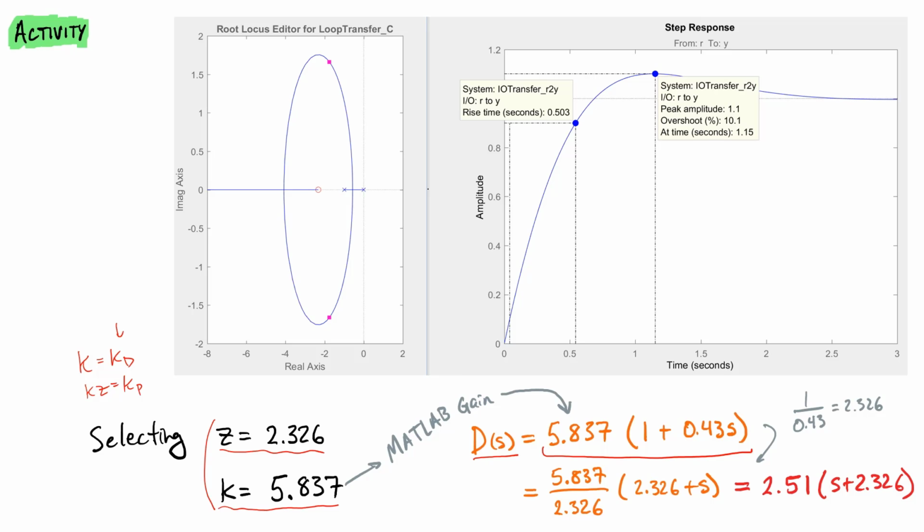And the reason why these are the important values is because our control law U, what our feedback control law U is, it's going to be KP times the error, the tracking error, where that is R minus Y, and that's going to be added to KD times the derivative of the error, and that is the derivative of R minus the derivative of Y. So we're literally plugging in these values and multiplying it by these two gains in order to get our input U. And so this could be, for example, the amount of voltage that we would add, or this would be the amount of torque that we would be adding, something like that.